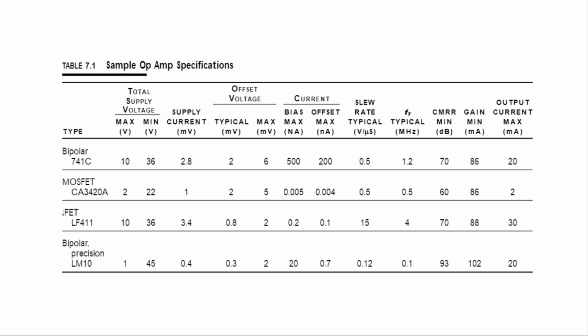Then there's voltage gain. A typical op-amp has a voltage gain of 1,000 to 100,000. However, the gain drops to 1 at a frequency called the unity gain frequency, typically from 1 to 10 megahertz, a result of limitations of the op-amp's internal circuitry. Output voltage swing is the peak output voltage swing that can be obtained without clipping, and slew rate is the maximum rate of change in an op-amp's output voltage with time. At high frequencies, the magnitude of op-amp slew rate becomes more critical. A general purpose op-amp like the 741 has a half volt per microsecond slew rate, a relatively small value when compared to higher speed models that can get to 600.